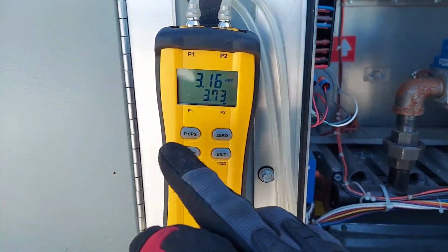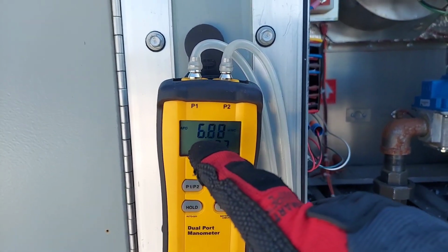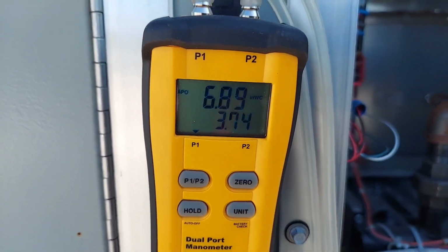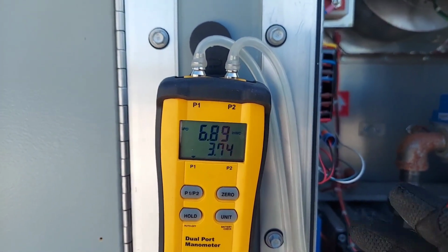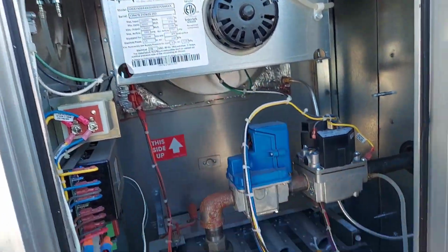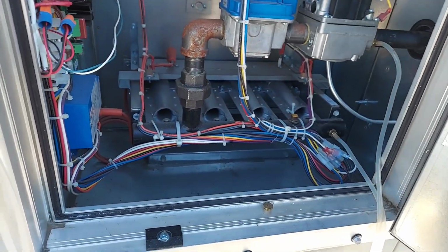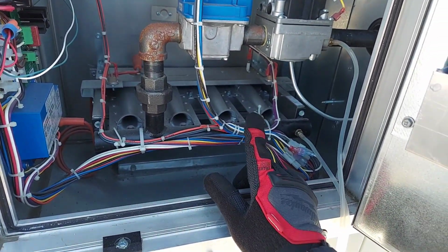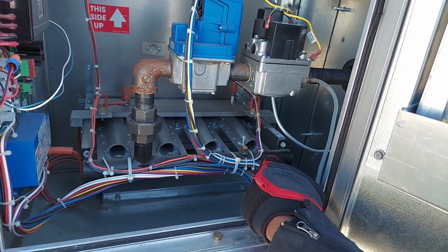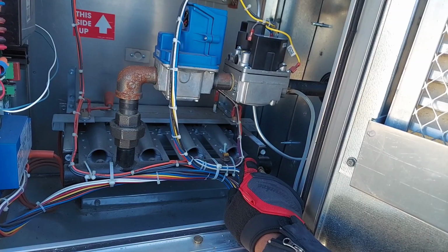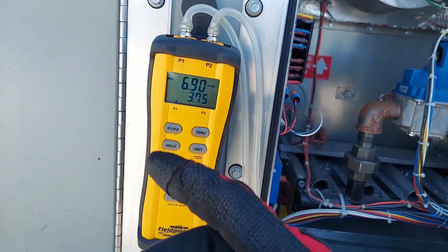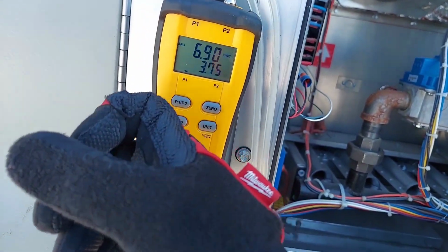It goes around, comes around, and look, you see my supply gas dropped a little bit, didn't it? So yeah, hence the reason why you want to leave your supply, like I said, not at the minimum. If you're entering at 5, you're gonna be in trouble. It's gonna be a struggle to maintain proper manifold pressures if your inlet gas pressure is at the minimum, because at any given moment that will fluctuate based on load and supply and demand, you know what I'm saying? So that's what it is.